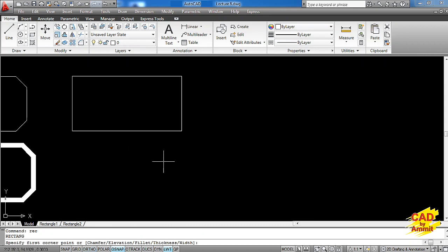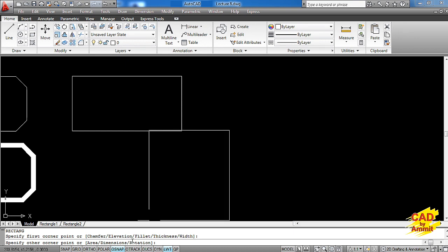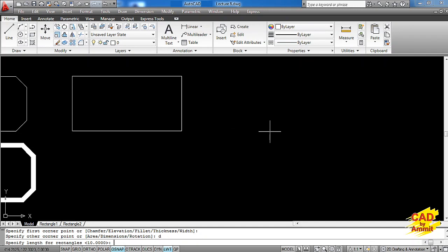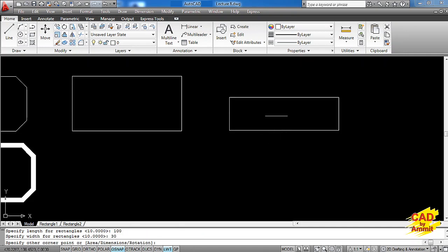Afterwards, then in a rectangle command, we give the first point. After that, we get three more options, friends. I'll quickly run through these options. First option is dimensions. I'll be taking the second option first of all. For the dimension option, I'll type down D, enter. Now here, friends, software will ask for both the dimensions. The rectangle has two dimensions, length and breadth. This will be asking for length first of all. I'll give 100 suppose. Asking for the width, I want to give the width as 30, enter, and here it is. We get the rectangle.